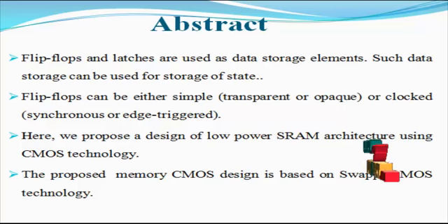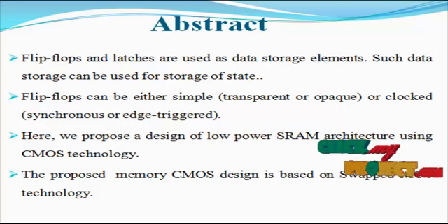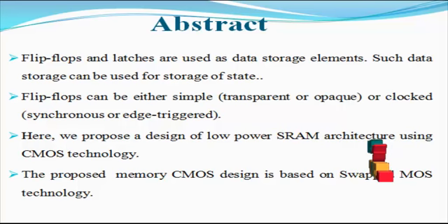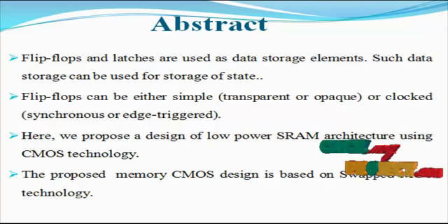It is still volatile, meaning that when the power is removed from the memory device, the data is not held and will disappear. The operation of the SRAM memory cell is relatively straightforward. When the cell is selected, the value to be stored is held in the cross-coupled flip-flops. The cells are arranged in a matrix with each cell individually addressable. Most SRAM memories select an entire row of cells at a time and read out the contents of all the cells in the row along the column line.